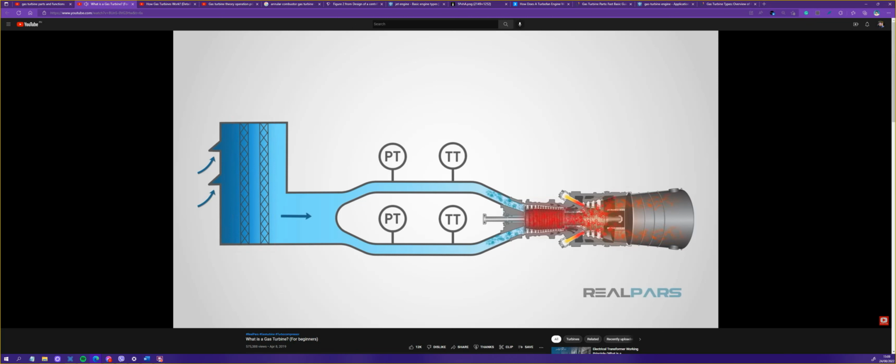Also, proper instrumentation is mounted on the air duct to monitor the draft pressure and temperature. In harsh environments, the air might need to be preheated or conditioned. Also, differential pressure monitoring of air filters will warn the turbine operator of filter clogging.